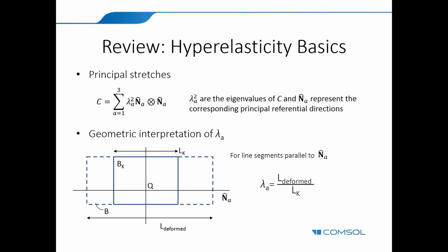So my only suggestion there with regards to hyperelasticity is that everything that we discuss today will be a part of such a model. But as far as mesh is concerned, you'll have to take a little bit of care. We can talk about that mesh when I do a demonstration, and we can talk about the meshing in FSI as well.